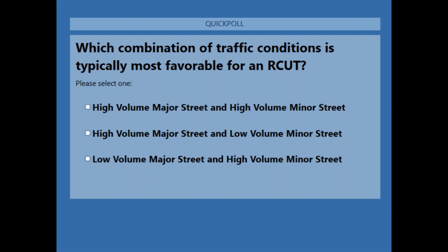Next question: it seems like it might be difficult for trucks to make the U-turn in a timely manner without a signal. Are there truck volumes that might be problematic? Great question. So yes, truck volumes are certainly a major consideration. The U-turn maneuver can be designed geometrically through the provision of a bulb out or a loon, which I am going to show coming up when we talk about design.